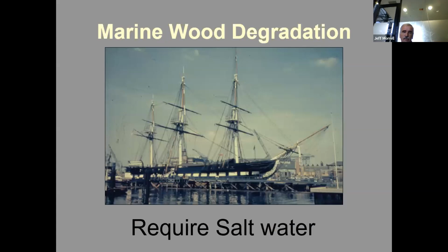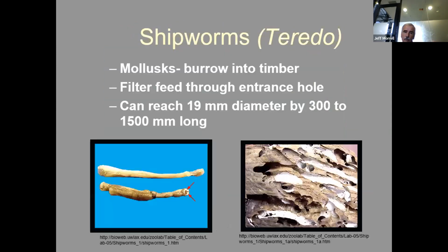I want to just briefly touch on marine wood degradation because it can be locally important in some areas. All the marine wood borers require some salt water, but that can be quite low, so you can have saltwater intrusion well upstream in an estuary. For example, around Brisbane, we see marine borer attack almost all the way up to the University of Queensland, where the saltwater does move up periodically, and you do see timber evidence. There are three different groups of marine borers we deal with.